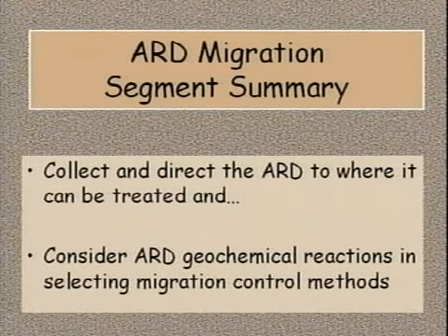You can also apply these techniques to keep ARD from mixing with sources of good water or to promote runoff, as in the case of subaerial tailings deposition. You should also remember to consider the geochemical reactions that might occur when selecting construction materials. So that concludes our discussion of ARD migration technologies.